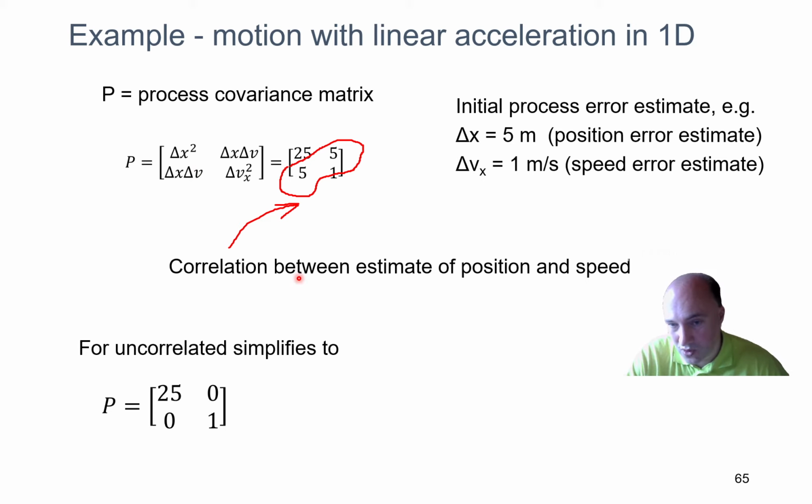If you are certain that there is no correlation between those two signals, if they come from independent sensors, you can set this to 0. By zeros here you say, okay, my variables are not correlated, so they are not mutually dependent. I will show you also in a calculation example what the contribution of this covariance is. It might be significant, but it might not be. In some cases I will use zeros here in order to simplify the calculation.